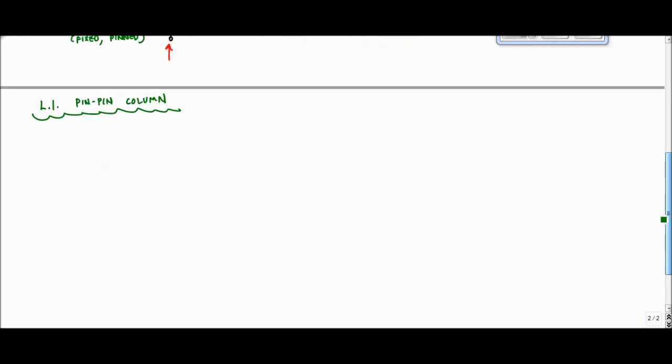I'm going to put a roller over here like that, and another one here like this. Is everyone okay with that? I just want to isolate it so this point can only move up and down. So that's one end of my column.